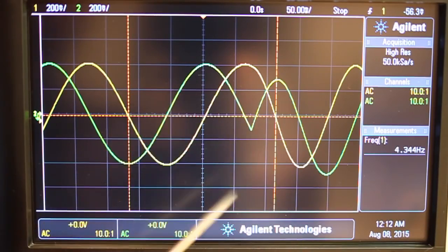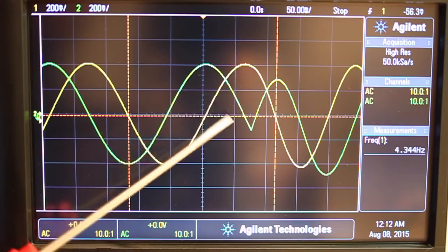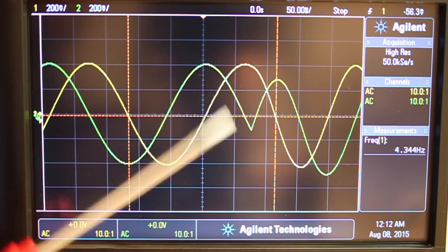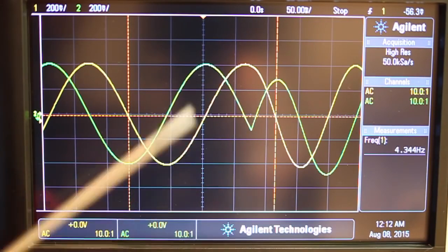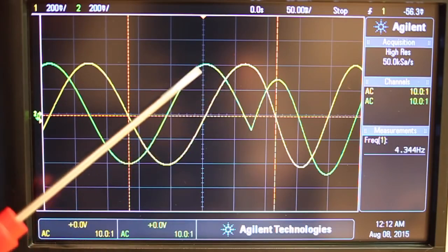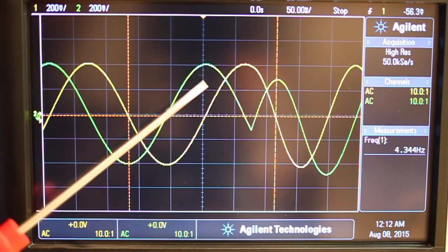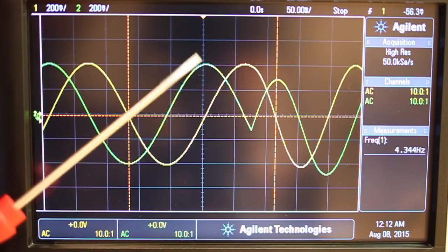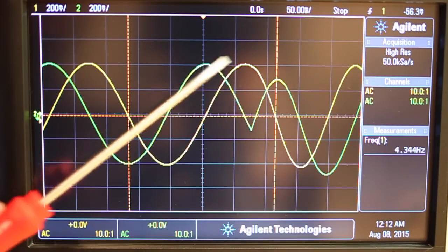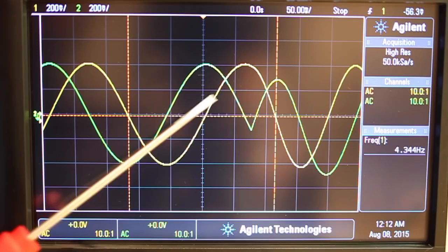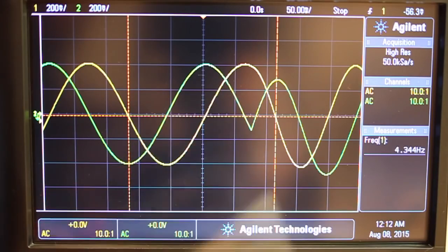So this I and Q stuff isn't just weird, abstract, imaginary math stuff. It's a real thing. We can actually take these I and Q components and construct signals with them, and we can take those signals and deconstruct them down into the I and Q, and we can see that I and Q behave exactly as Euler's equations predict.